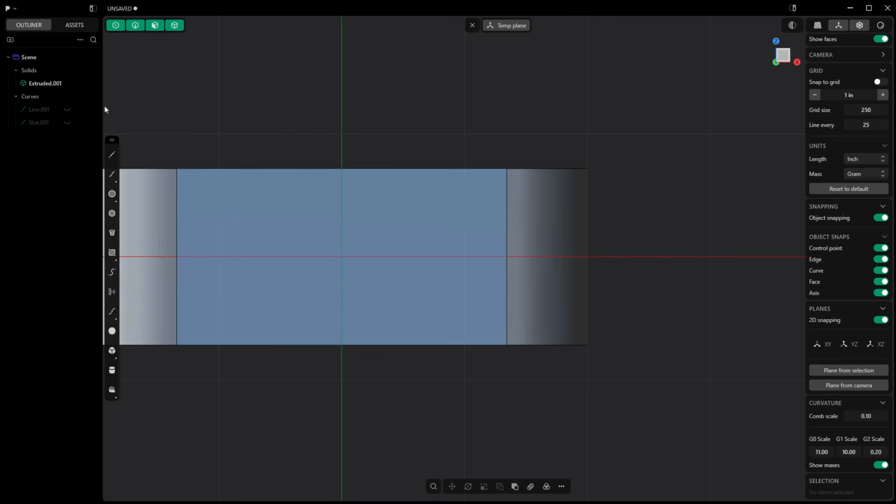We're going to zoom in, and I'm going to create a circle, and I'm going to begin dragging the circle down, and I need to define the diameter of it. So we're going to hit tab. And the diameter of this is going to be based slightly on the diameter of 1/2" PVC, which is not actually 1/2". The trade size 1/2" does not represent the actual diameter because, of course, why would it? Now, as PVC pipes and as Schedule 40 and Schedule 80 pipes change sizes, that does shift as you cross a certain point, outside of the purpose of this video.